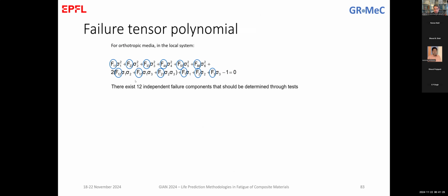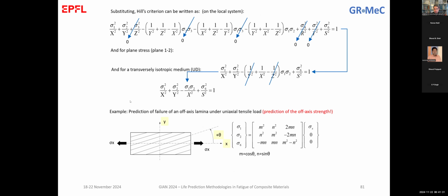If you remember, the Tsai-Hill criterion, I'm going briefly back, considered only the tensile failure at X, Y, Z directions, and didn't talk about negative force, or what we call in composites the differential between the tensile and the compressive strength.